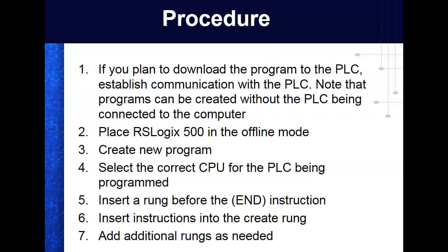online and offline. To modify the program, you can't modify the program while you're online with the PLC. And you can't download into the PLC, so you got me thinking. You can't download into the PLC unless it is in the program mode. And I can show y'all how you can switch it.